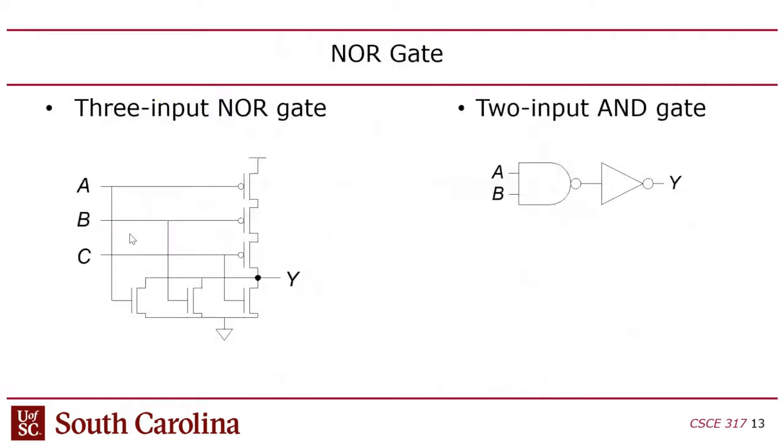The reason I'm saying closer and not connected is because if you have, for example, a NOR gate, the nMOSs are in parallel, so each of their source terminals can be connected directly to ground. And this is going to become relevant a little bit later when we talk about the total capacitance.